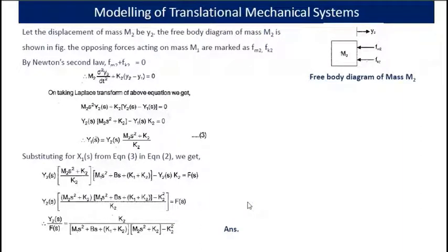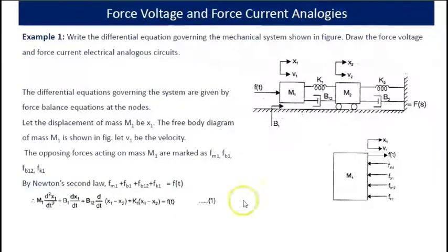So in order to find the transfer function, we have to take the Laplace transform. First, we have to write the differential equation, then take the Laplace transform, then find the transfer function. And we can do some problems in force voltage and force current analogies.